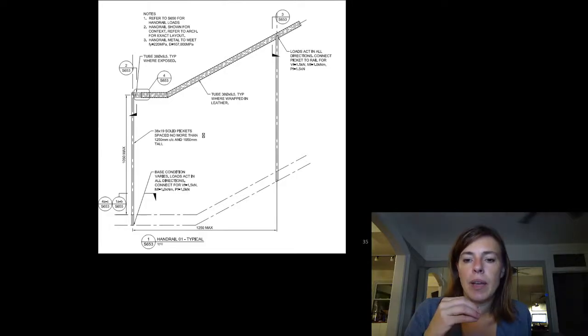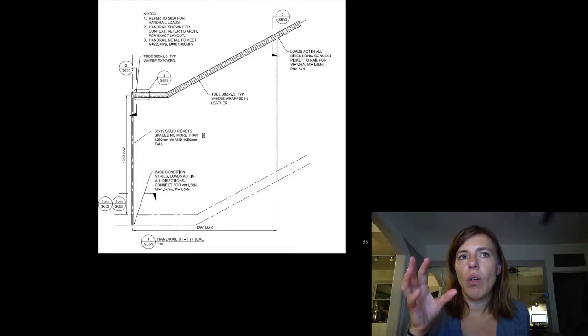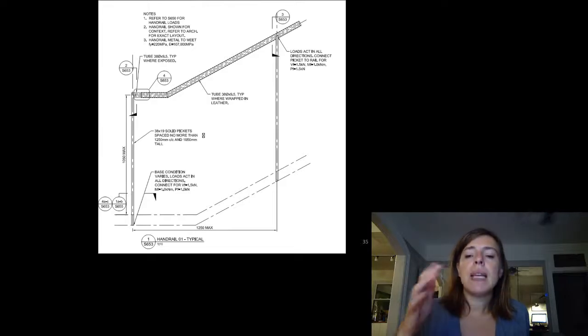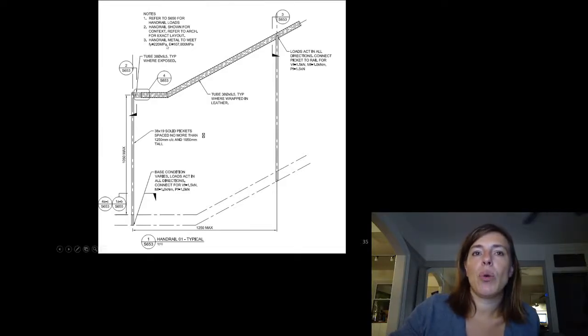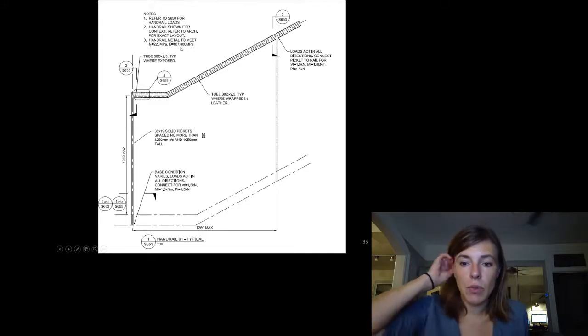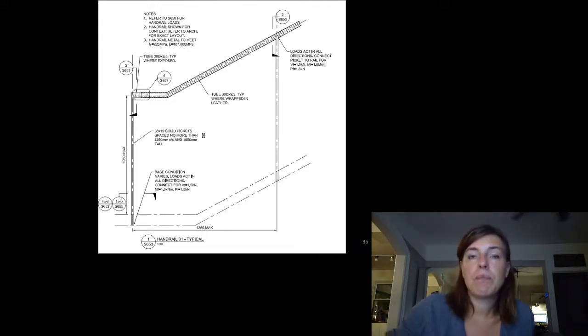They had another steel they wanted to use, and then they wanted to do this alternate aluminum that had different properties than the normal aluminum. So in the end, what I did is I took the bronze material properties and I said they could design it out of whatever they wanted as long as the material met the strength requirements and the stiffness requirements of the bronze that it was originally designed with.